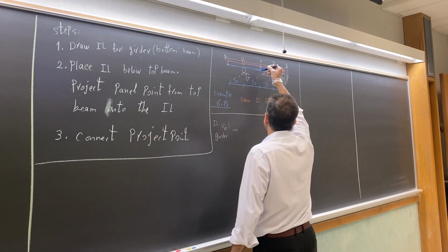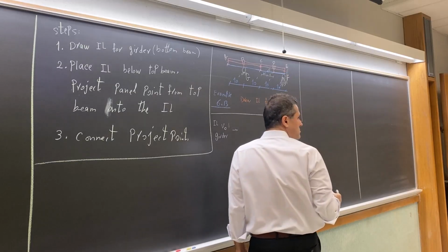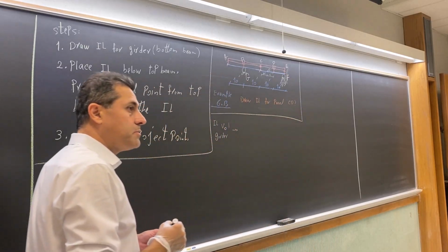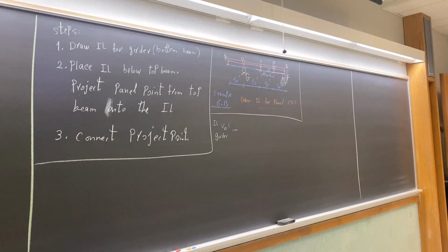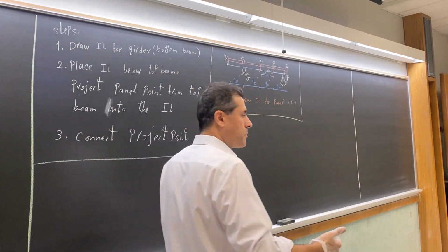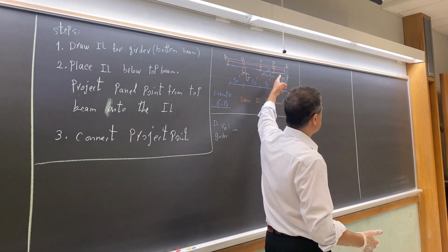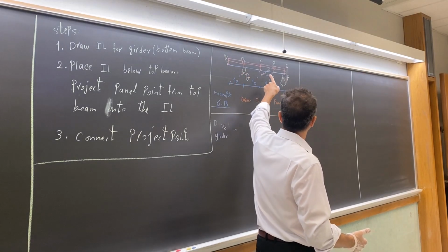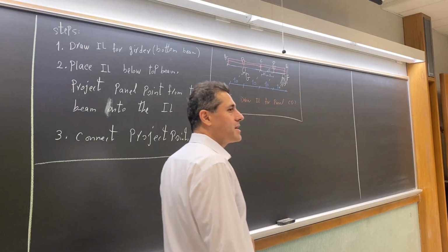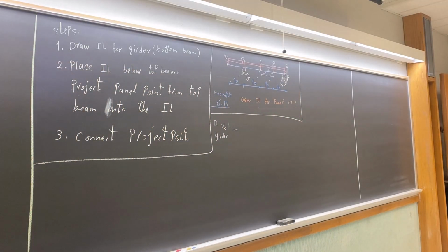This is the girder. Remember our practice so far? Forget about today's lesson. Consider the previous session. You have this blue color beam. You want to draw the shear force at point O. What was the method? You cut it at point O, Mueller-Breslau method.